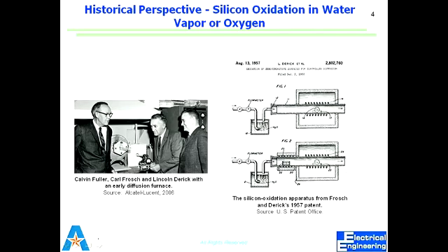So we coat that thing with a noble metal, which safeguards whatever is below. Same is the reason we want to do silicon dioxide. Number one, electrically we want a material which is insulating. The other is we want to put a protective layer on top which doesn't result in further oxidation of silicon. So it's a passivation layer. It's like painting a metal thing with a paint which doesn't let corrosion or rust happen. So the oxide is done to electrically isolate parts and to passivate the substrate, to cover everything so no more reaction occurs with anything else.